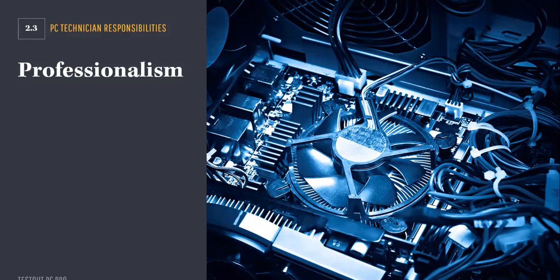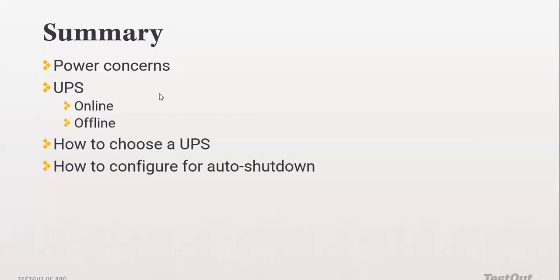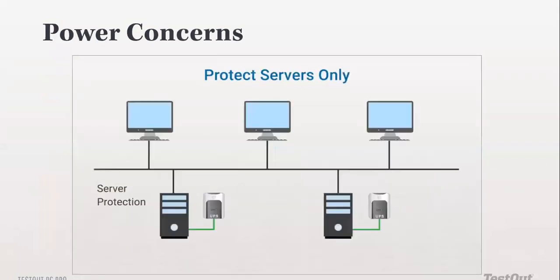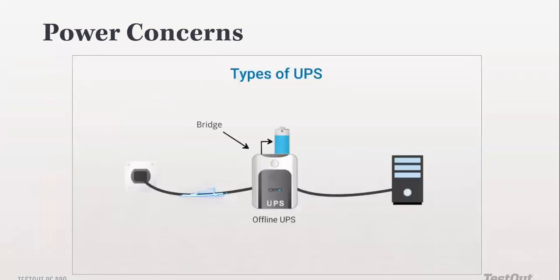Yes, thank you. In an online UPS, the battery is not separate. You can see that the battery right here is being charged and kept in. In an offline UPS, it only comes in when power has gone off. But this other one, the battery is constantly being charged and it is also providing power to the PC. That's why we call it online. It is not offline and waiting to come on when power goes. It is constantly online providing power. I hope you understand now. Yes, it is. Thank you.